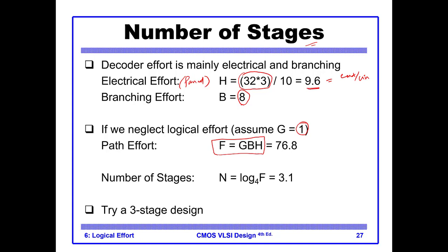When we are designing for the number of stages, we start with inverters. So always when we want the number of stages, we assume that all the gates are inverters.